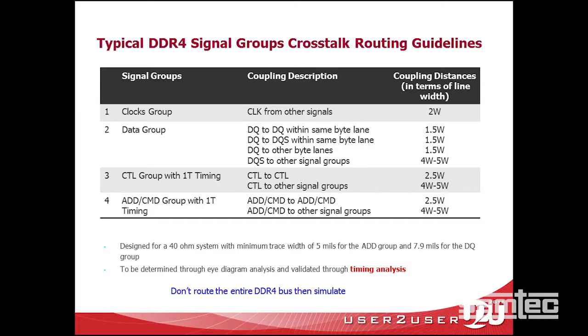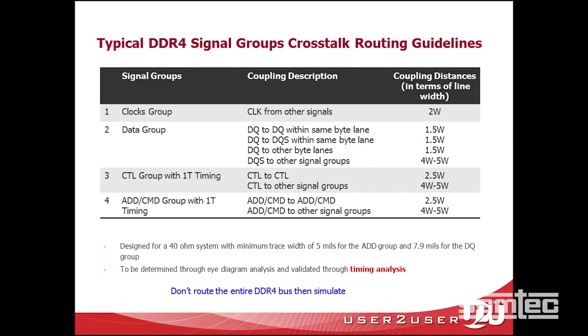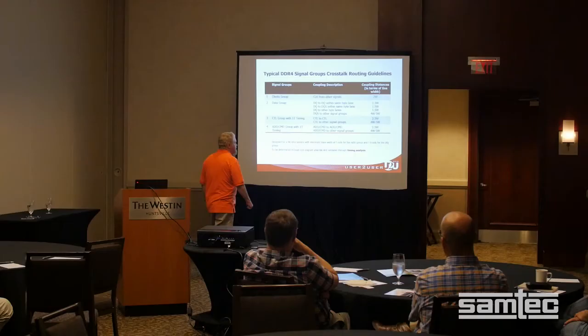And then the next one is, how close can your signals be routed next to each other? We would all love these to be minimum spacing. Love everything to be minimum spacing. In almost all cases on DDR3 and 4, you cannot route minimum spacing because the crosstalk is too high. Even on your motherboards, if you take your motherboards and flip it over, that's usually where a lot of the DDR is. They're not routed to minimum spacing. Look at the DQs and look at all those.